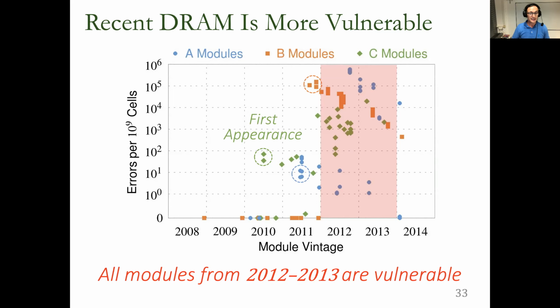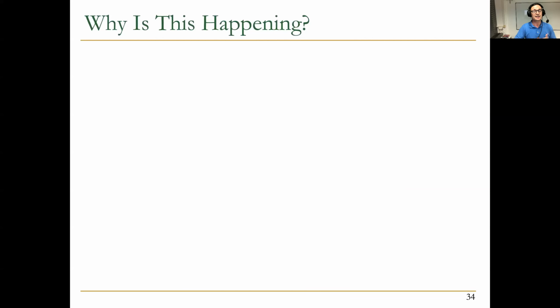But later, in 2010, 2011, 2012, 2013, as the cells became smaller and denser and the charge in the cells became smaller, these noise effects increased. The number of activations you had to induce to actually cause a bit flip reduced significantly. And we were able to do that within a refresh interval. In our paper, we mentioned the number 139,000 for single-sided hammering, for example. So clearly this should not happen.